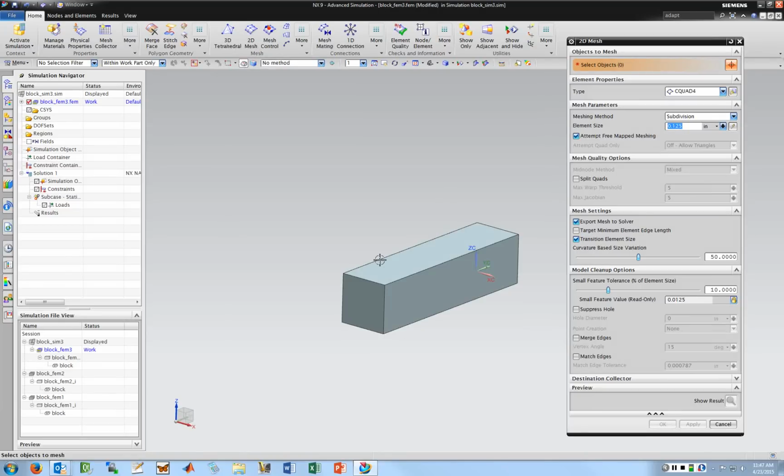If this was actually just a piece of box tubing, so a square tubing, and it was thin wall, 16 gauge or something like that, and I just drew it as a solid just to make it really easy to draw. But whenever it comes to FEA, I actually want to mesh it as if it was a 16 gauge steel tube. I can do that. I don't have to actually draw the cross section and then try to figure out how to do a 3D tet mesh with that. I can basically do a 2D mesh along all of the edges of it, and it actually works out quite well.